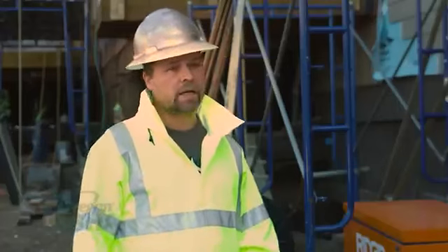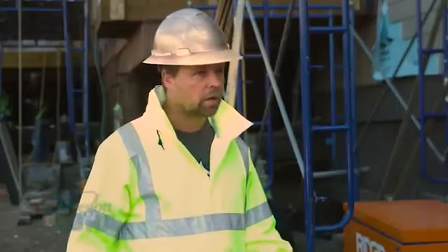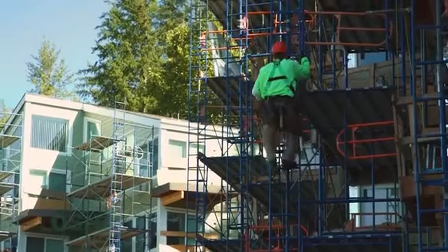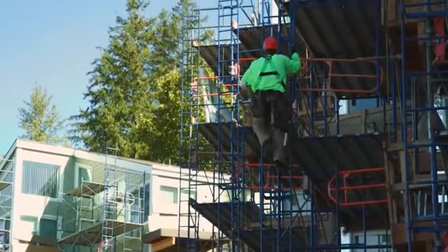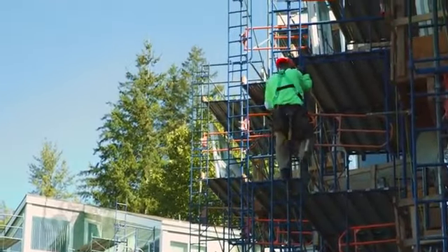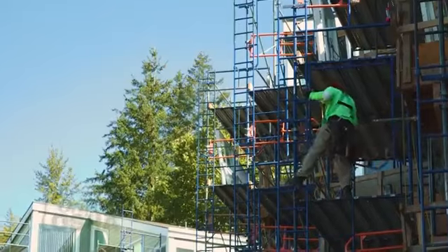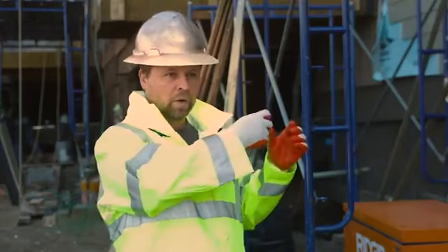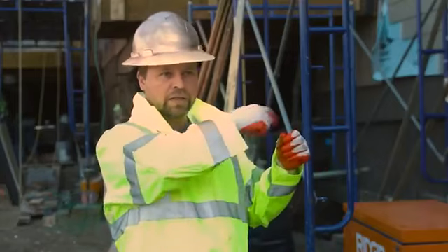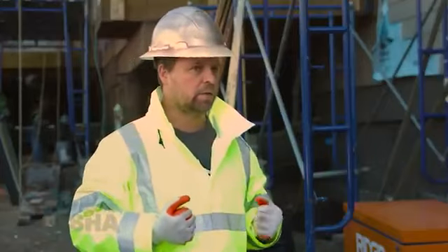We always tell the guys, hey, every time you climb on the scaffolding, really take a look at how things are set up. We do an inspection pretty often, but as a general rule, anytime you climb, especially on a ladder, you want to make sure the bolts are properly secured and the nuts all the way tightened up, so you don't have anything loose on the scaffolding. If you notice anything out of place, do not use it immediately. Bring it to your supervisor's attention and start correcting the issue.